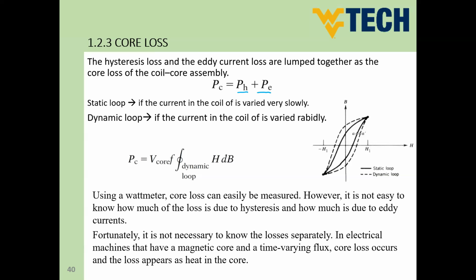And again, the last part is just to know something about the core loss, but it's not going to be considered for questions or numerical questions in our exams. This is just to know that the core loss has two main parts: hysteresis loss and eddy current loss. How can we reduce eddy current loss? We can reduce eddy current loss by creating insulated sheet cores, not solid cores. This is everything we need to cover in magnetics in order to understand the remaining topics in our class. So we are ready to start in the next class on the transformer topics.